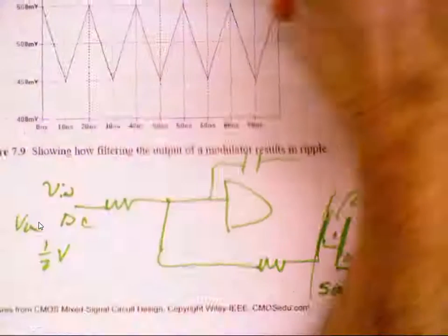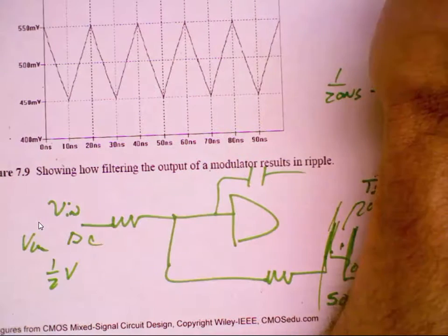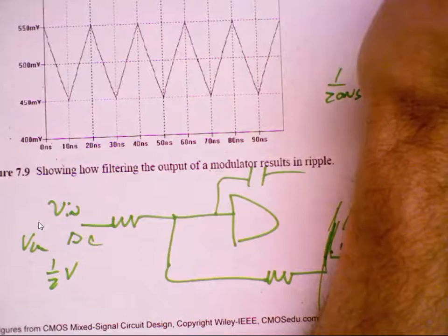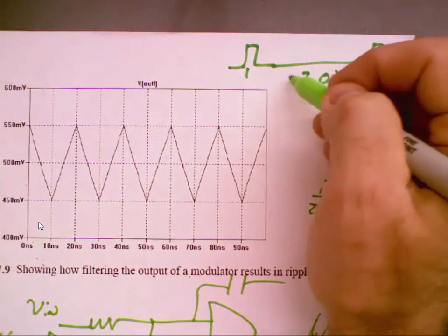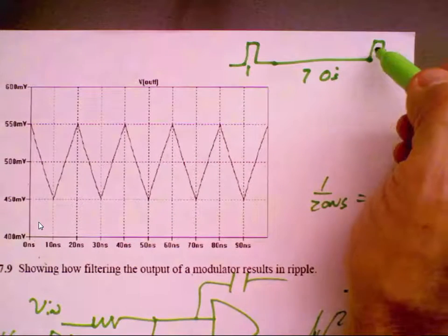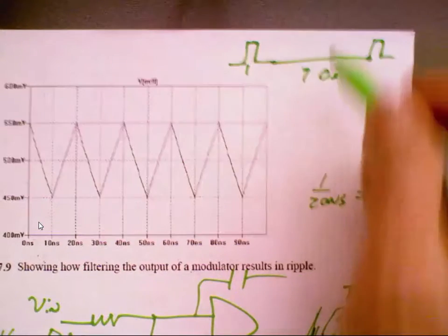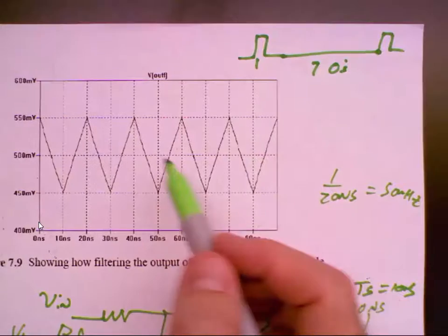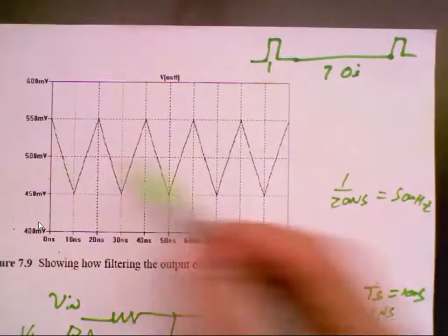All right, so what happens when I have a 1 followed by 7 zeros? Let's just put that in there. The frequency content is going to have a higher frequency component and a lower frequency component. The longer the repeating stream, the more likely I'm going to have that repeating in the base spectrum. Here I have 1 0 1 0 for the output, bouncing back and forth. Now, of course, if I filter more, I reduce that.